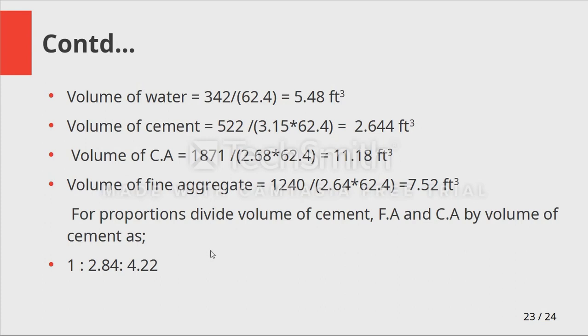I mean you should decrease it, because if you are getting less compressive strength, then you should decrease the water to cement ratio. If we see the relation of water to cement ratio, it has an inverse relation with the concrete strength. So you should decrease the water to cement ratio in order to increase the amount of cement. Increasing the amount of cement will lead to an increase in compressive strength. So this way you can perform the trial and error procedure.